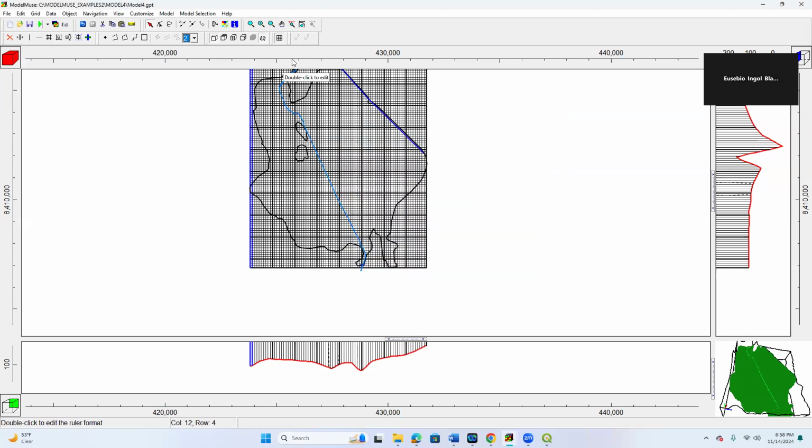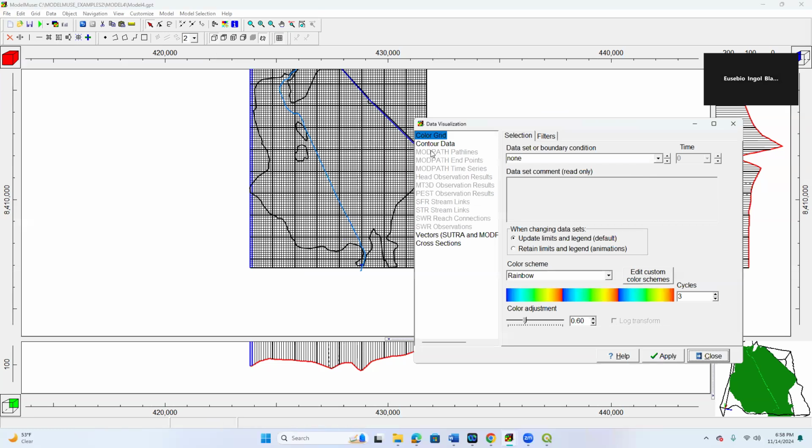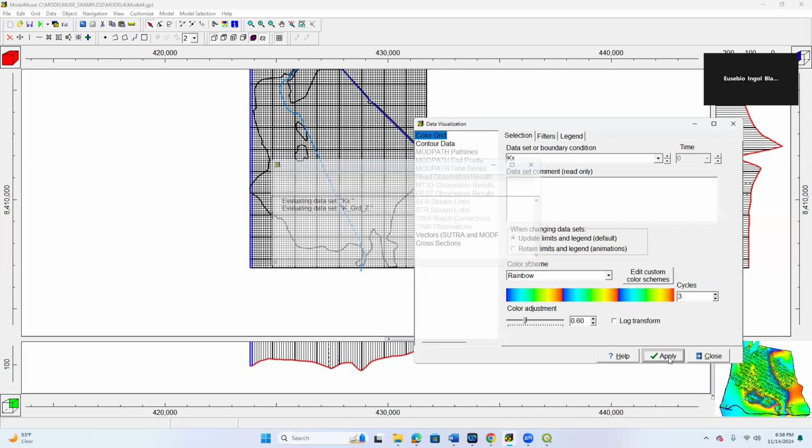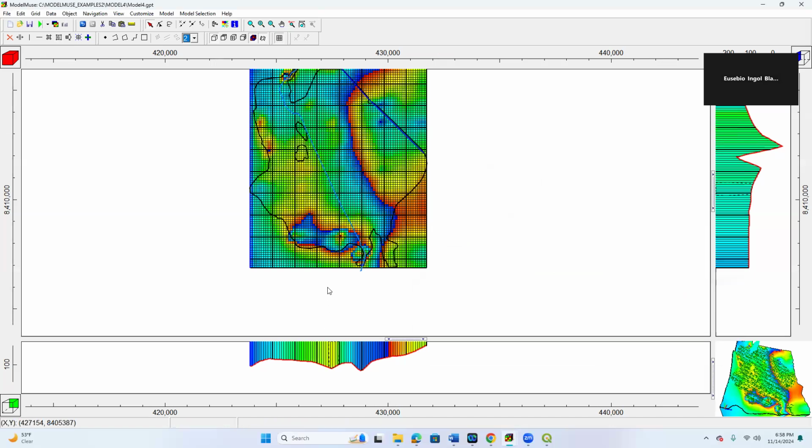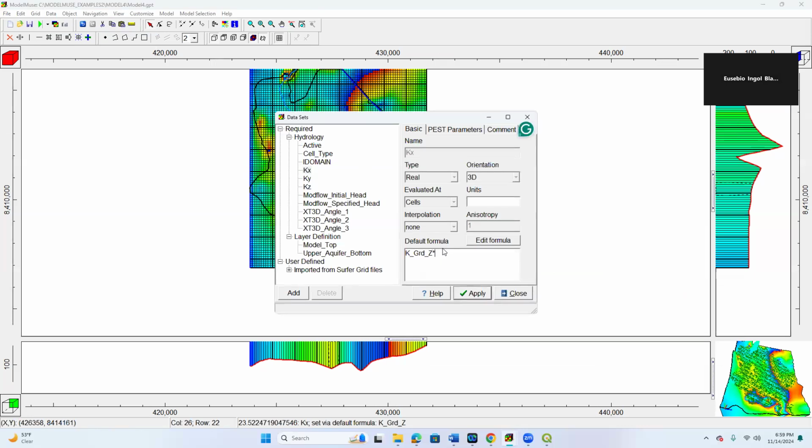And then if we go to see our hydraulic conductivity here, for example, and then Apply, you are going to see the different regions. Look at the bottom, where we have the value. That one has very small values. For this specific study, we need to multiply our data here. Go to data edit, and then multiply this value by 10, like to convert.